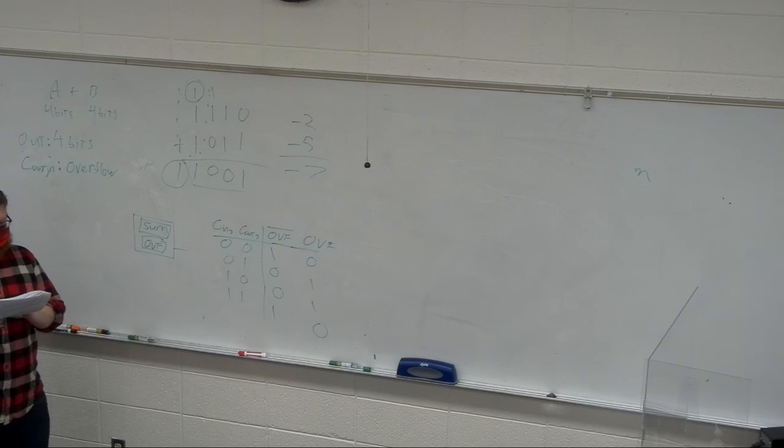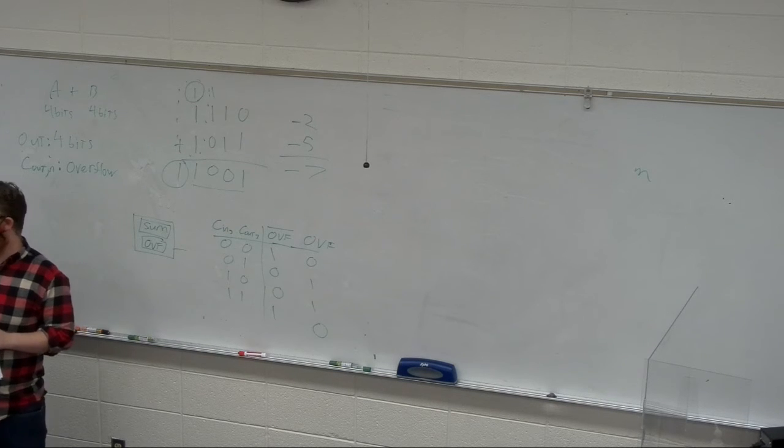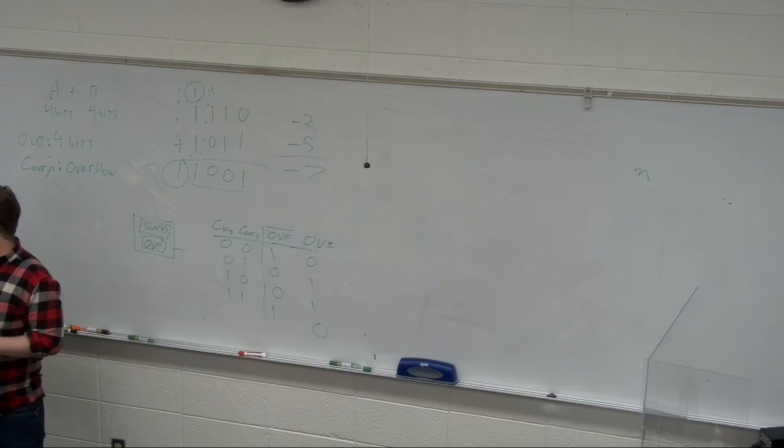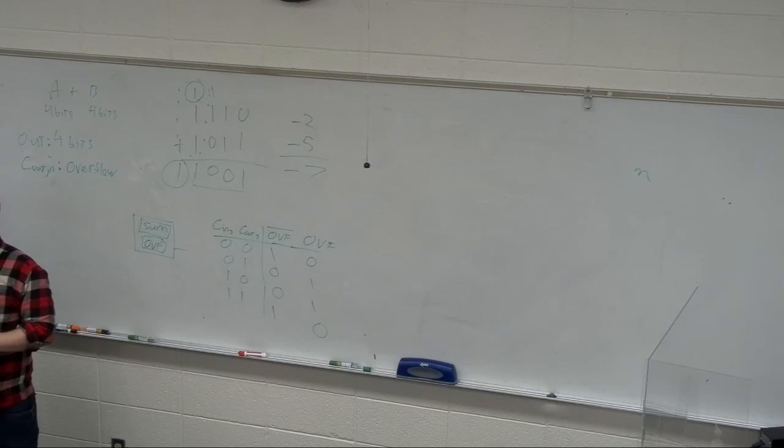There are examples of this. I did example 8. Nope, I didn't. Examples 8.3 and 8.4 if you want to look at some of the 2's complement addition. Yeah. So would you just put the overflow one as the last gate of it? Exactly. So you do the simple adder beforehand. Full adder, full adder, full adder, then end on a full adder, but then you just attach an XOR to the carry out and carry in.